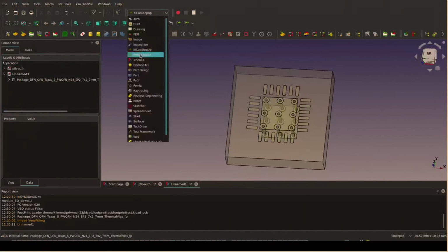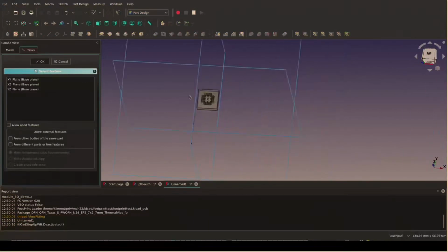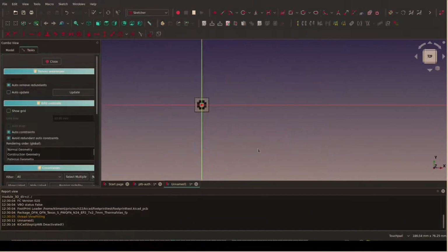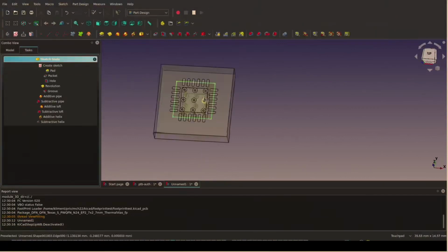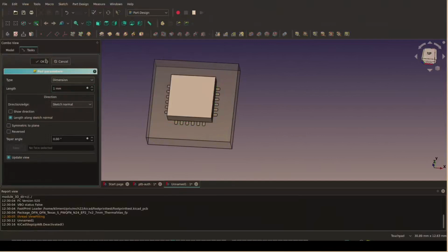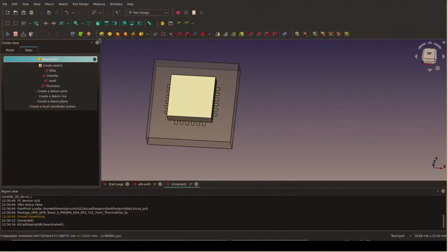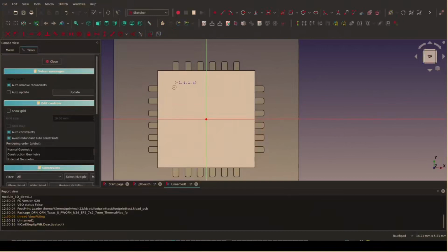And we're going to then design a model on top of it. And this is now the standard FreeCAD design process, where we're building basically a sketch and then extruding that sketch. So I'm making a rectangle here, and you then look on the datasheet and check those dimensions and enter those in here. So this one is supposed to be 4. And then the height of it is supposed to be 1, so we're going to extrude it to 1 millimeter. And then we're going to add a pin 1 indicator in the top left. So that's the orientation that the footprint was in KiCad.